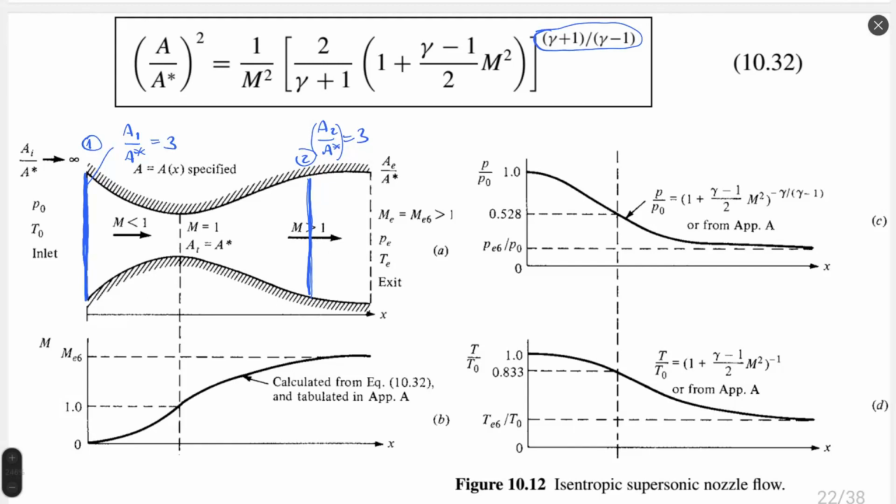So let's calculate Mach number. Let's calculate then pressure and temperature ratio. I can define that my stagnation pressure is 10 atmosphere, for example, or 10 bar, not important, because we always use dimensionless ratios. And stagnation temperature, let it be 1000 Kelvin.